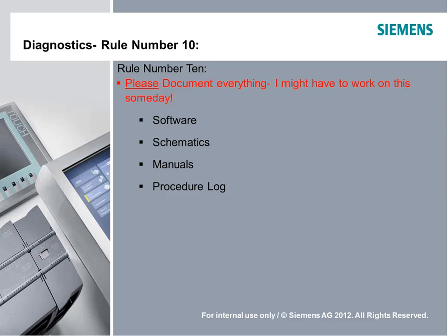Schematics. If there's a wiring change, or sometimes sensors are not the same polarity and you have to change the wiring around a little bit, document that, please. Redline a schematic, write it in the procedure logs of the machine and so forth. Any manuals that the machine has with it, mark them up, put a sticky on there, do something to let somebody know that you've been there before and this is where you found the issue.